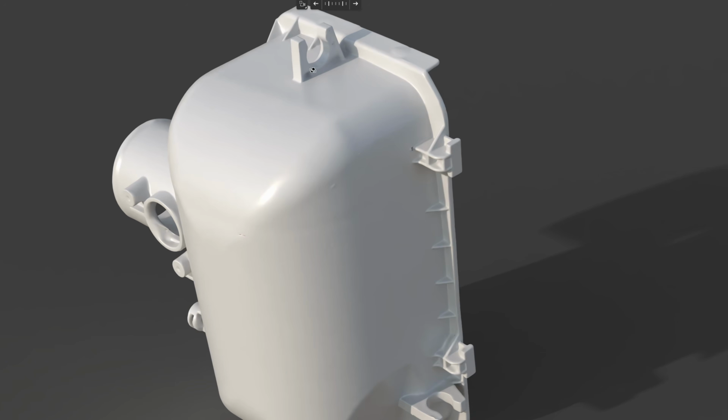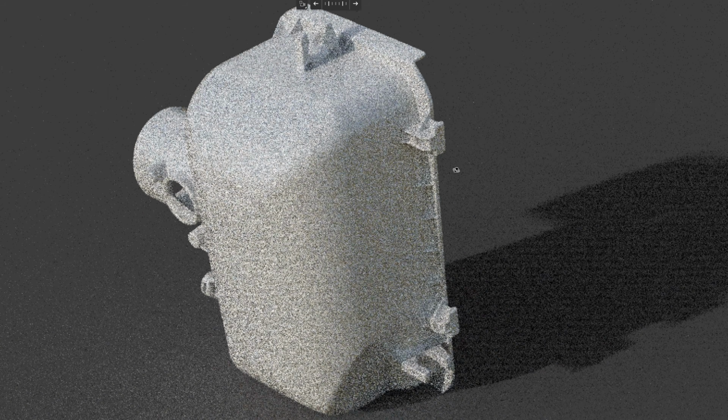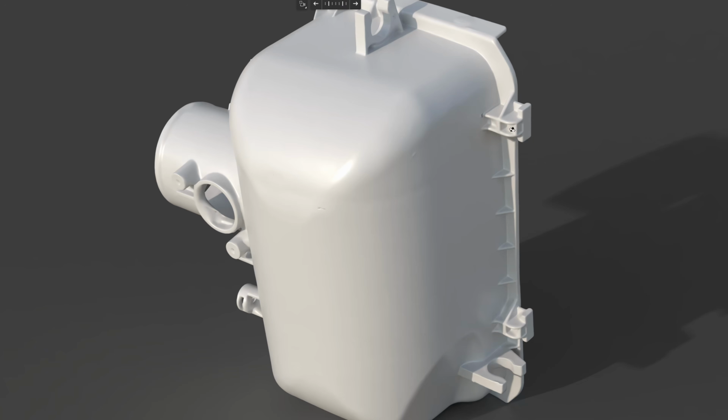There are also 2 holders for the pipes. I can include that in the model as well. And if you look here, I will fill this pocket with solid material because I don't have to make the thin stiffener wall like this. It's going to create a complication when you make a 3D print.